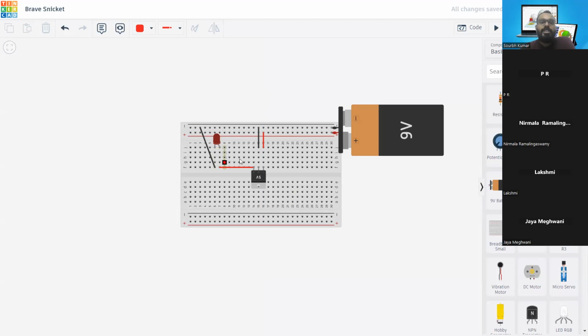So now I just connected the wire directly to the negative terminal, and one of the wires is connected to the out pin of the 7805 regulator. Let's hit this start simulation button and see what happens. So again, the voltage is reduced, but the current flowing is not reduced because this LED is not ideal to be utilized with 5 volt as well.